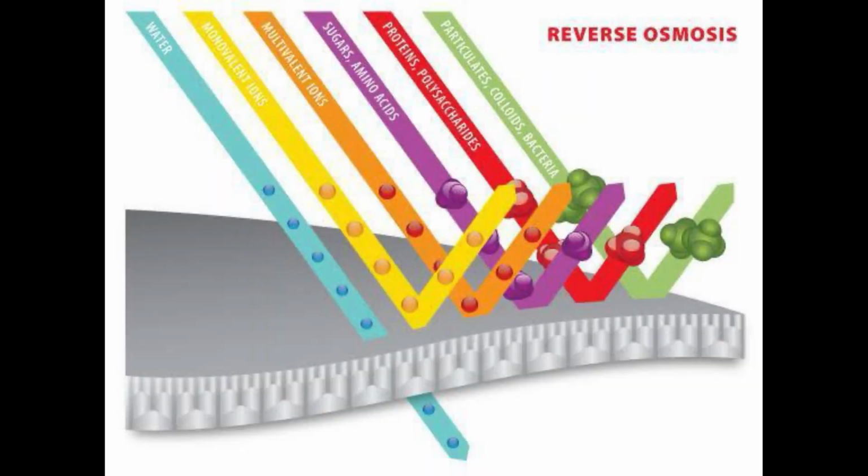So, reverse osmosis filters have a pore size of around 0.0001 micron. After water passes through a reverse osmosis filter, it is essentially pure water. Reverse osmosis also removes most minerals that are present in the water. Reverse osmosis removes monovalent ions, which means that it desalinates the water.